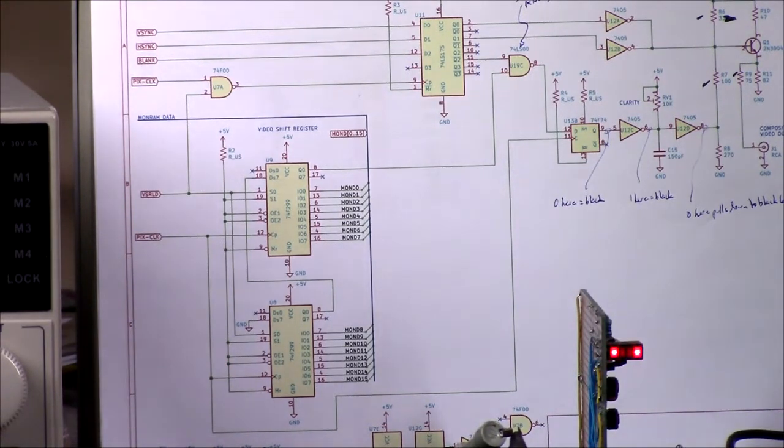So another little blue wire on the board. Now I know some of you out there are probably thinking, oh, come on. Don't expect us to believe that he actually made that mistake. You did that on purpose so that you would have a video to make. Well, I have no comment on that. But I'll have to move that from pin 9 to pin 8. It was pin 5 of this one, from pin 9 to pin 8, and that should invert the video, and so we'll do that and come back to it and see if we get a different level.